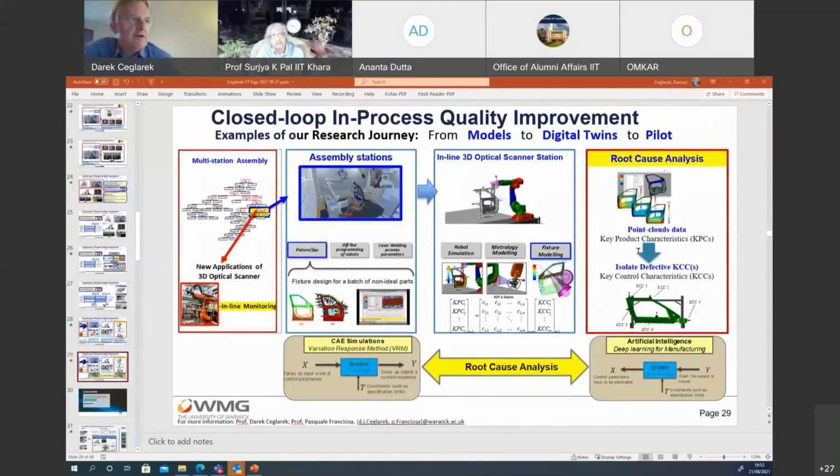From the point of view of vacuum, we have some discussion, but not in this specific case, for aluminum-lithium alloy. Why? Because it's expensive, actually. Our goal is to have a naked laser only, if possible, so no wire if not needed. We are driving towards a minimum number of additional components, such as wire or inert gas. We are doing vacuum chamber welding right now, but for a different purpose: to weld the chambers using laser, which have a vacuum inside.